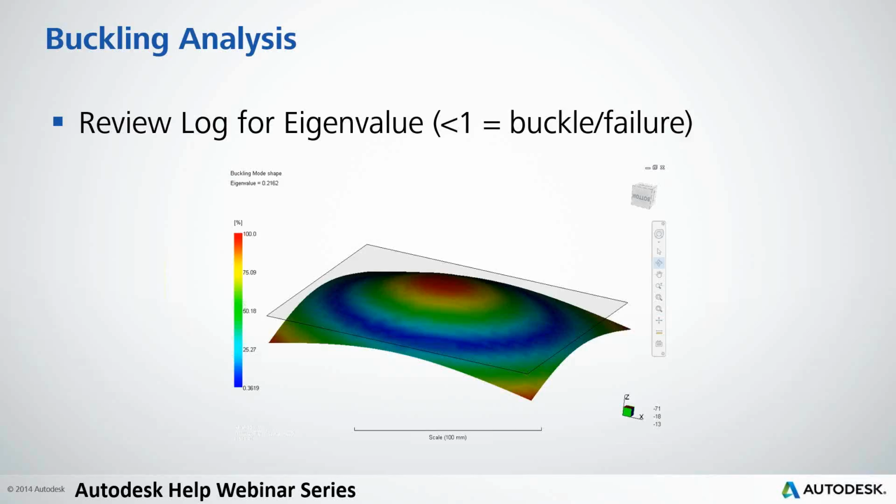And again, as Beth mentioned, if it is less than 1, then there could be a failure, because essentially I like to think of it kind of as a factor of safety. If you're applying one load, then that's going to be 100% of the load. If you say have a value of, let's say 3 or 4, then you would be doing about 300 or 400% of the load in that particular area of the tool or part.